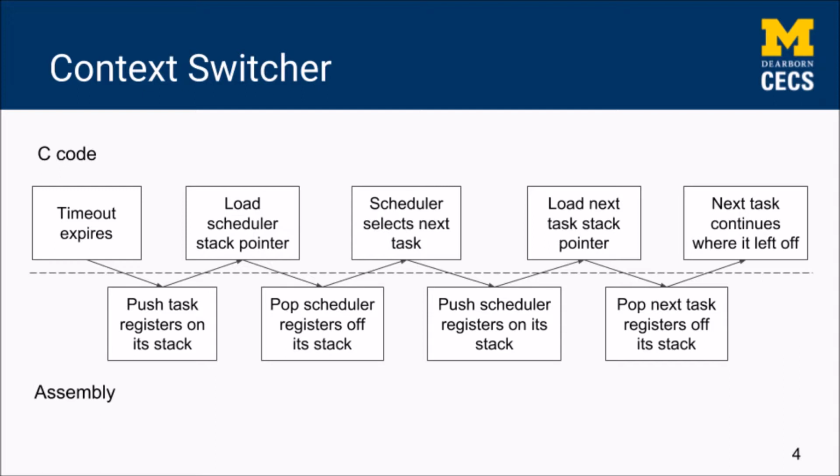For switching between C and assembly, we use global variables. We used the extern keyword to import one into the other, so functions and globals from C and subroutine labels from assembly. And then we also use the export keyword in assembly to make its subroutines available to C. As well, we didn't really use it in the context switcher, but certain other functions use it, that assembly instructions can have data passed in or returned via register 0.